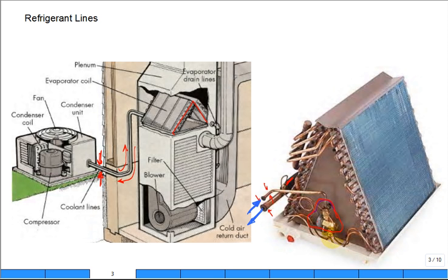But once it goes, now drops the pressure right across here, and now you have a distributor. So it's got 1, 2, 3, 4 lines, and they snake over, and they start feeding sections of the coil, and it goes back, do a loop, back, do a loop, back, do a loop.